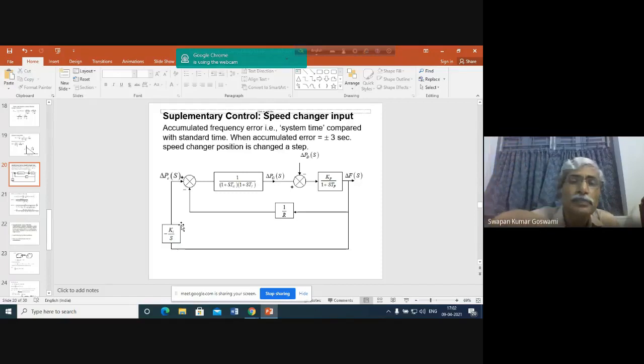As more power is being delivered by this generator, other generators will now be restoring their initial power setting value. In this way, generators will be able to operate in the most economic operating condition, and the system frequency also may be controlled.